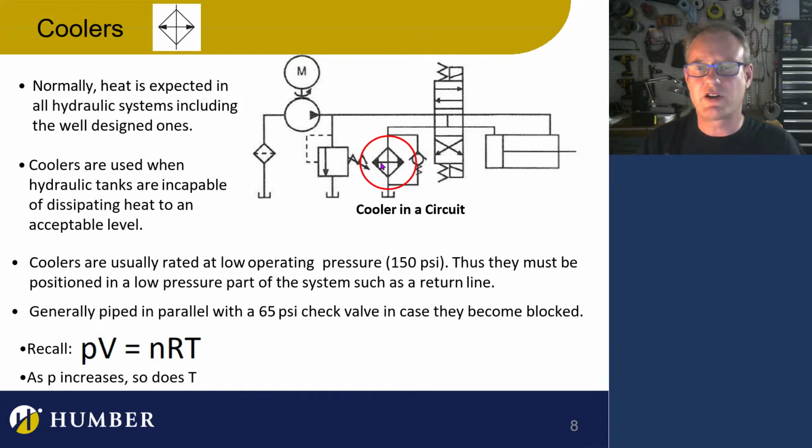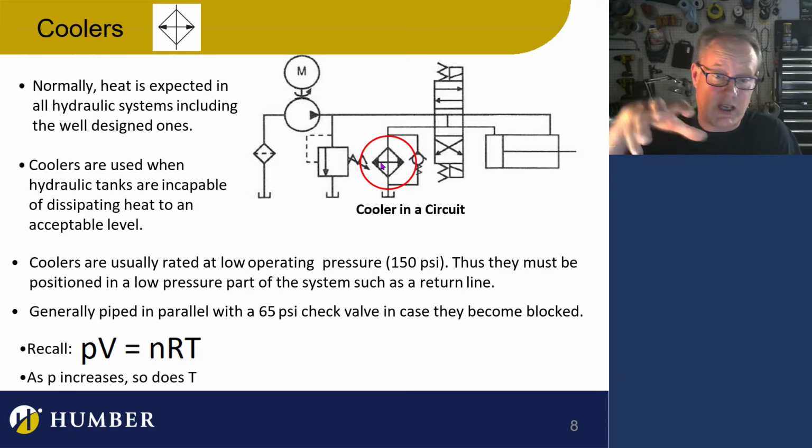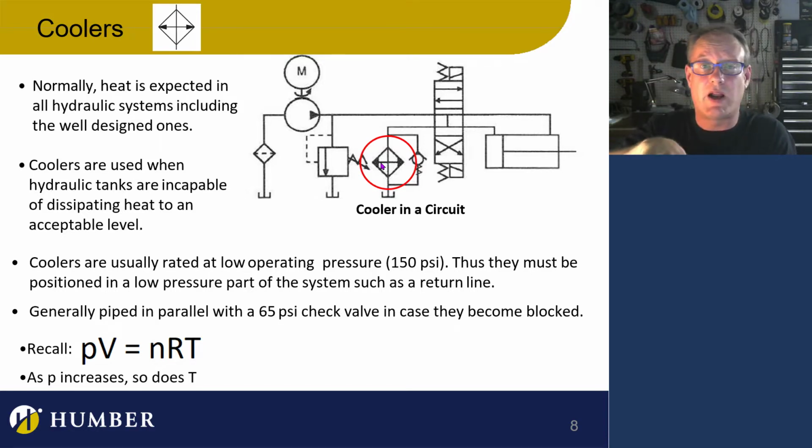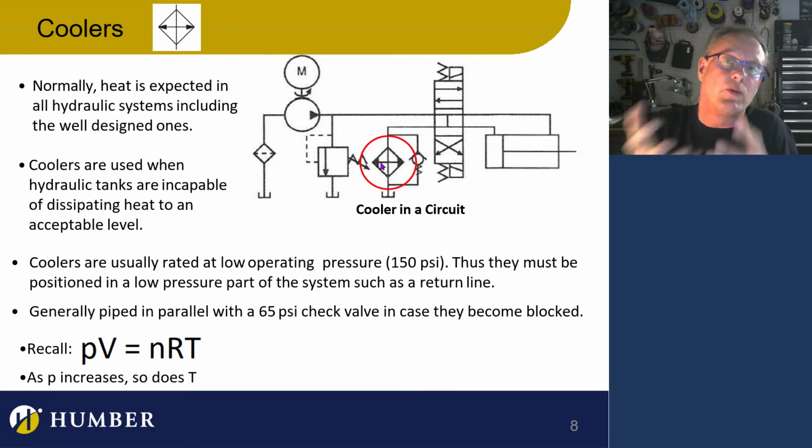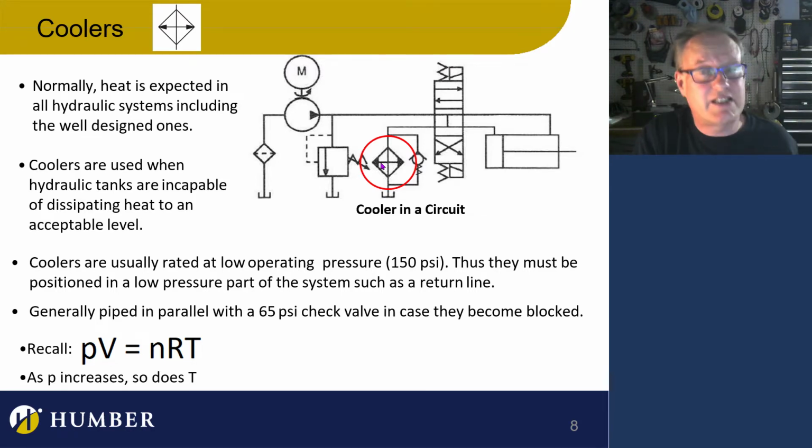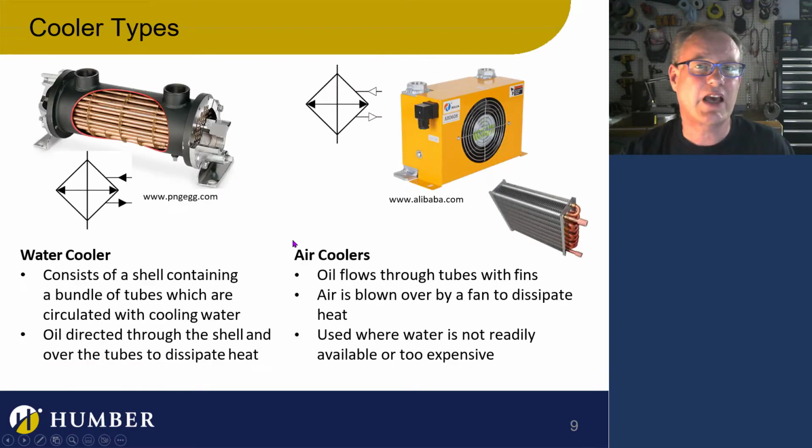So if your system is warm, if you can touch a pneumatic actuator or a DCV and you feel that it's really warm, you've got to cool that down. Although that heat goes into the fluid, which goes into the tank, and then the tank sits there. If you are only using the fluid intermittently and you're giving it enough time to cool down in the tank, you don't need a cooler. But if it's running all the time, often you're going to need a cooler on your system to cool things down.